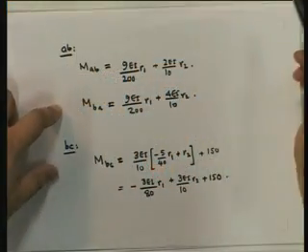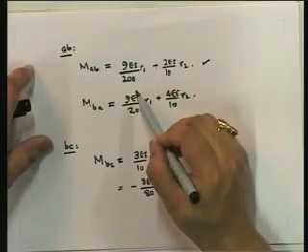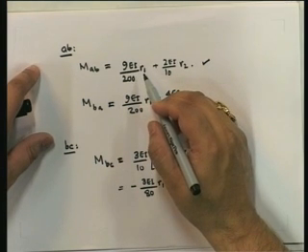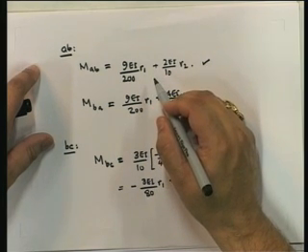Having done that, let us now write down the relationship for AB. Since the kinematic relations are the same, and the member force deformation relationships are the same, I have written down MAB and MBA. They're identical to what we had computed when the C support was fixed. It has no bearing on the member force deformation relationship in AB, and therefore I've just written down the value of MAB, which incorporates that theta AB is equal to 3 by 40 R1 plus 0 R2, and that theta BA is equal to 3 by 40 R1 plus 1 R2.